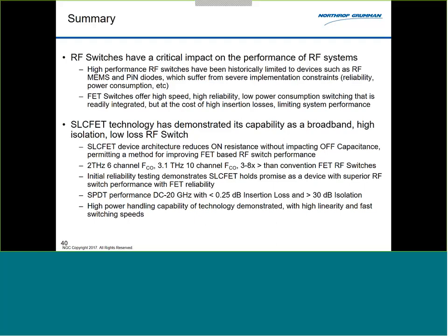And early in my career, one of the projects I was involved in was the power switch technology programs we had at Northrop Grumman, including our DMOSFET and some of our SIT work, doing the very high voltage, 10 kilovolt type switches. That's exactly the kind of trade where you're worried about switching losses, but those devices are a lot different. They have really large area devices, enormous in terms of footprint, relatively speaking, versus these devices.